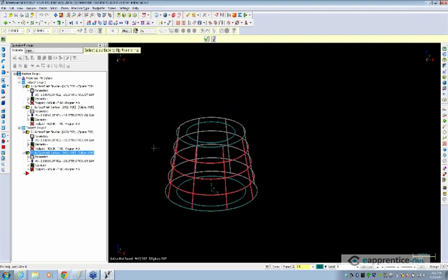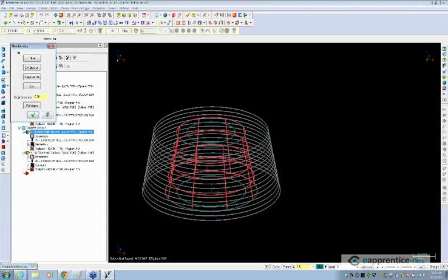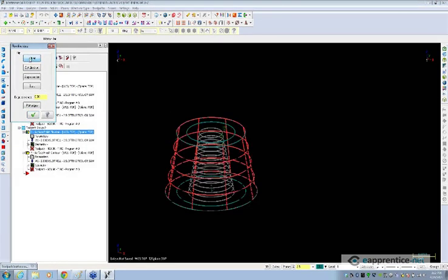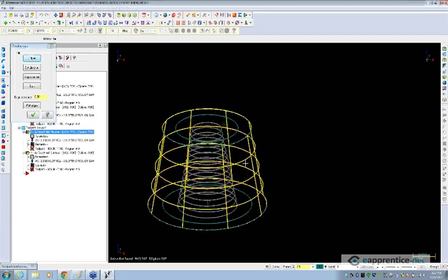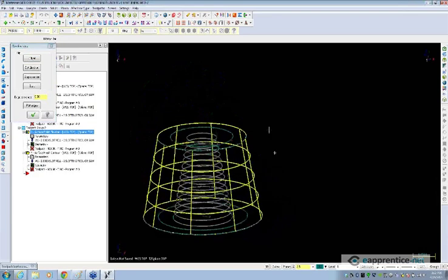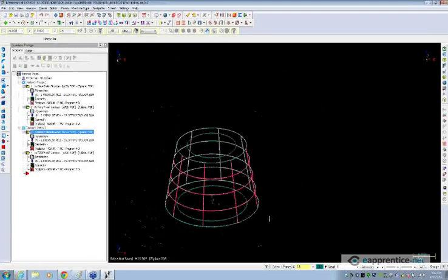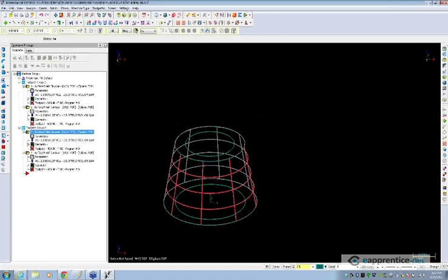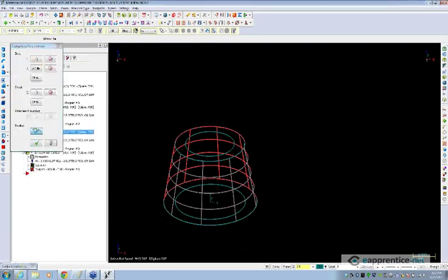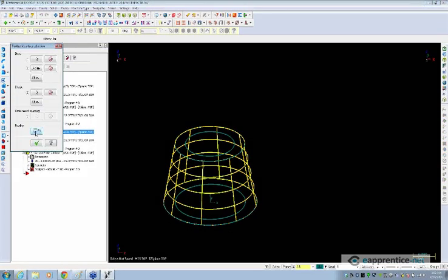So for example, if I flip the normal to the outside, and then we take our surface finish flow line, click on the geometry button, and click on the flow direction, the default is going to be having the cutting on the normal side of the surface. But there is the option to use the flip offset. So if you click on offset here, we can flip it to the inside, and we can cut the non-normal side of the surface with flow line. So it does allow you to do that, but it is a best practice to always have your surface normal set properly. So in this case, we would recommend going in, changing the normal back to point to the inside, going back into the geometry, and again, adjusting our flow directions.